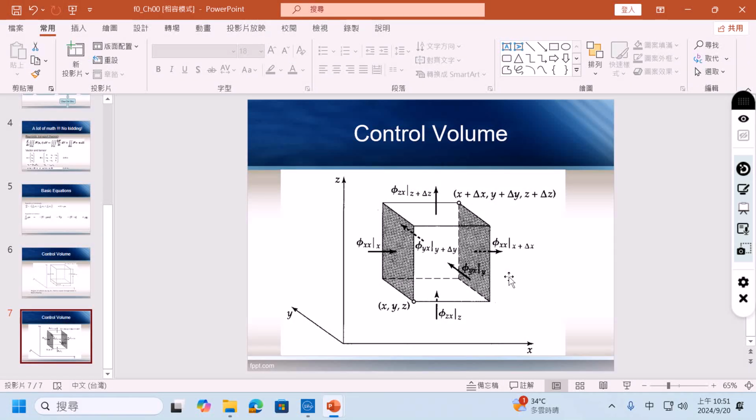We only take a control volume in the direction we are interested in. And that's shear balance. So shear balance is actually the reduced model of the equation of motion, because the equation of motion takes the control volume for all directions, but for shear balance, you only take a control volume for the direction you are interested in.